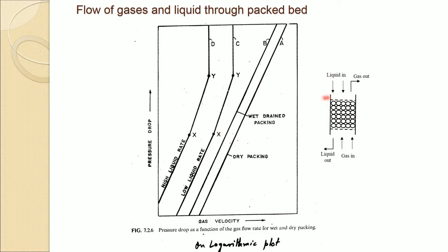Now, instead of just a drained packing, liquid flow is there. When liquid flow is there, it occupies the spaces between the particles through which it flows down and comes out. So, again it is occupying more voidage, more space in the packing, which creates more resistance for the gas to flow through, so pressure drop will increase.